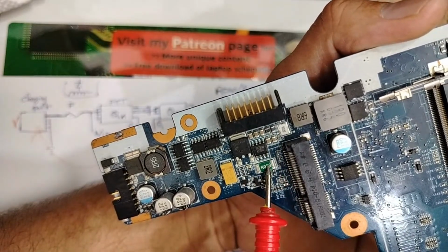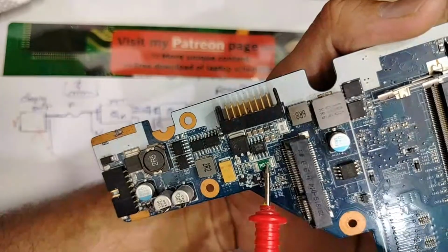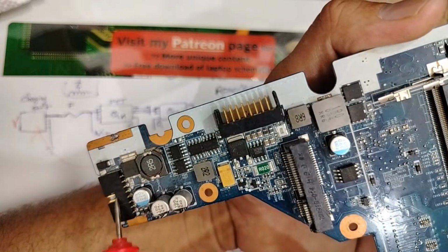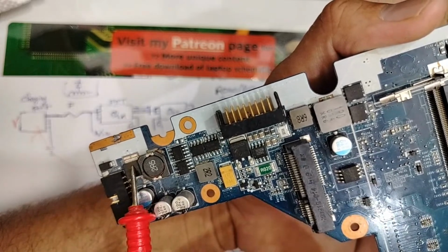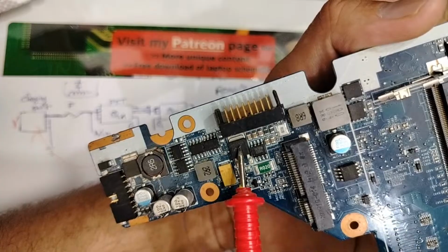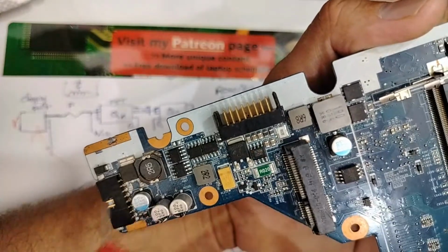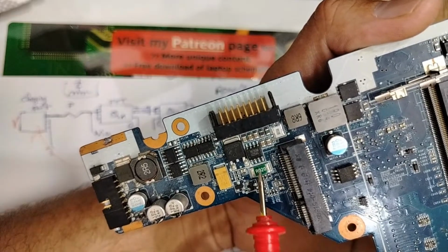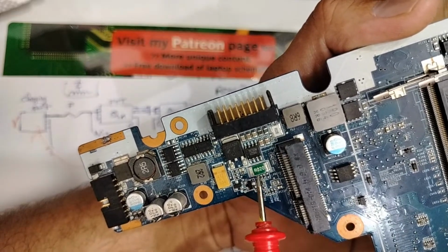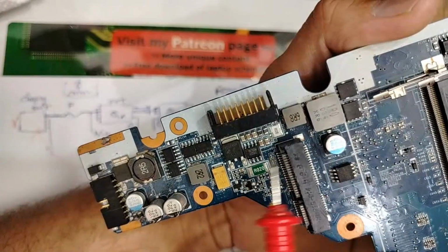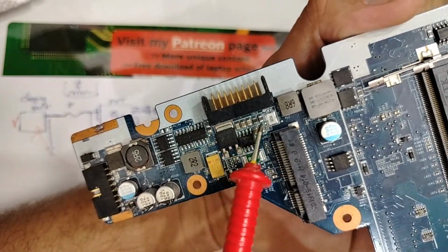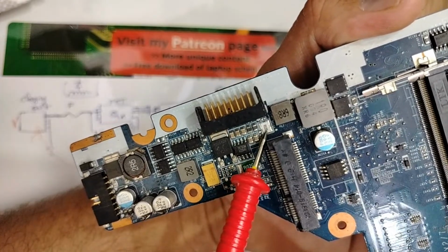The big one, always the big one, is for the motherboard. Here, the big one is connected to the power jack. Here we have the power jack, we have the switch. And this switch is for the battery. This switch is for the power jack. This CSR, current sense resistor, measures the whole current consumed by the motherboard. And this one is for the battery. Also, we have here R020.